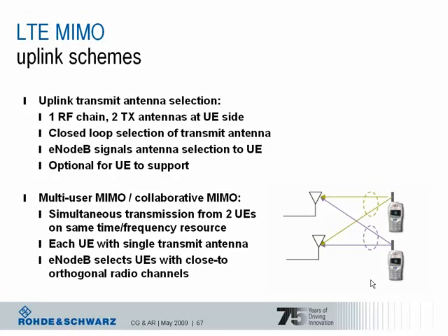Another scheme used in the uplink is the so-called multi-user MIMO or collaborative MIMO, supported in LTE, so two UEs actually transmit simultaneously over the same time frequency resources. That is indicated in this small picture, and the UEs are actually scheduled by the base station, so the base station needs to decide whether this is actually possible or not. And each UE just needs to have one transmit antenna in this case, as it's also indicated in this picture. But you can imagine that this scheme only works in certain radio conditions, so it's really up to the base station to evaluate that carefully.